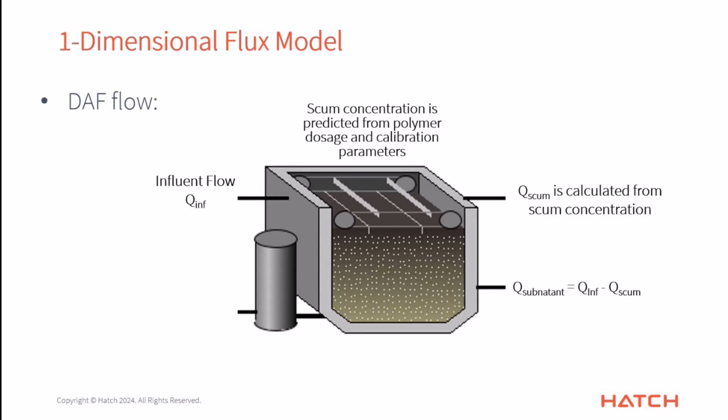So you're going to have the loading coming in, you're going to have the properties of everything, and it's going to predict the effluent concentrations and the split of the flow coming out that side as well. Now, I should take one moment to point out that many DAF units also have settleable solids being removed from the bottom. We don't have that in our model, and it's on our list of things to add at some point, possibly for the next release of GPS-X.